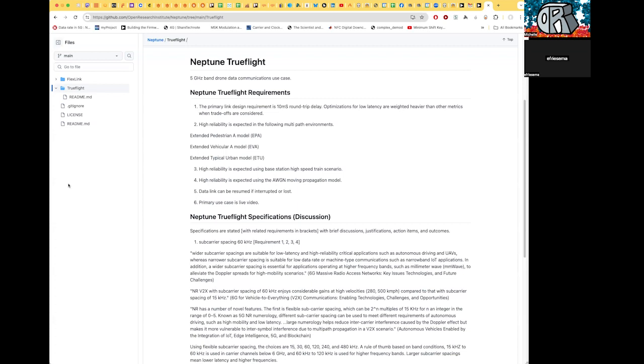Since the specification includes OFDM, that determines that we'll have a bunch of signal carriers. Then are we going to use LDPC encoding or something else? Forward error correction can obviously help reliability, and it directly affects all the other things too.